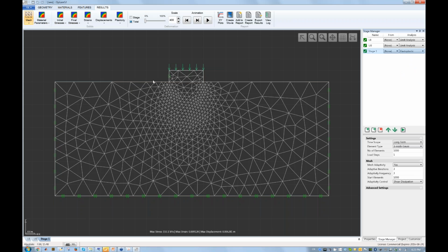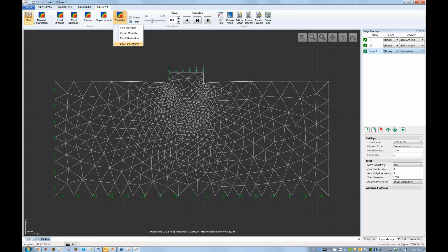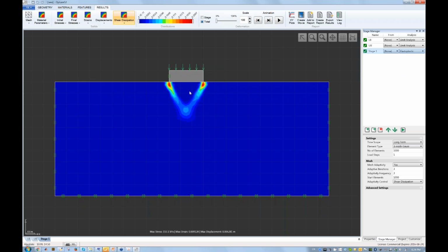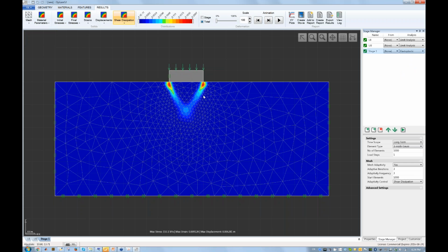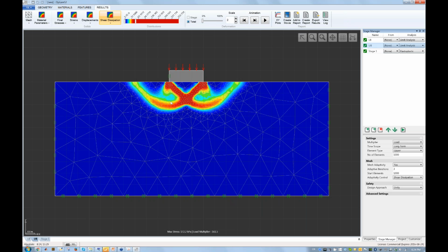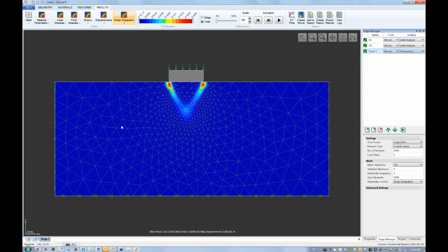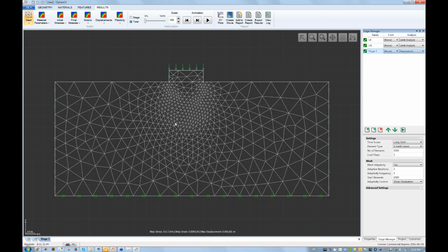And in this case, you can see with the elastoplastic analysis, again, this is sort of how the footing moves. Let's plot the plastic strains again. You see, of course, they're much less developed than in the case of the ultimate limit state. So here we are well before the ultimate limit state, and that's reflected in the mesh as well. It's adapted not only to capture failure, but also to capture the elastic deformations you have in this problem.